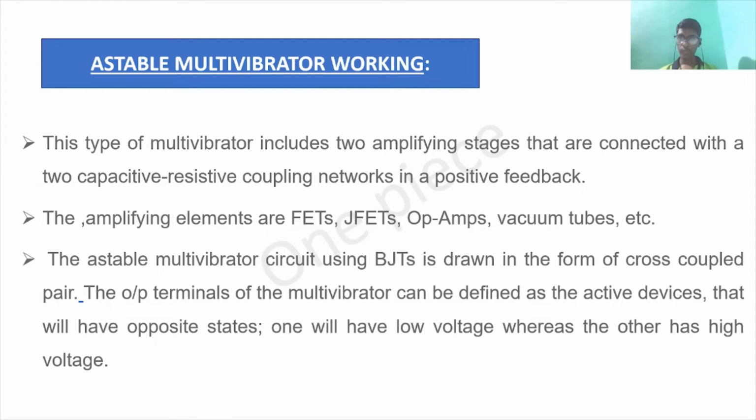Next, the astable multivibrator working. This type of multivibrator includes two amplifying stages connected with respective capacitive-resistive coupling networks in a positive feedback. The amplifying elements are FETs, JFETs, op-amps, vacuum tubes, etc.